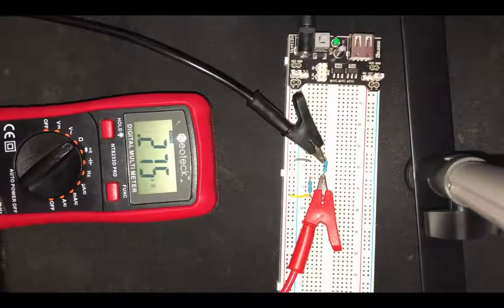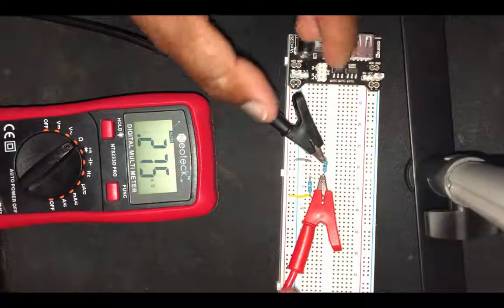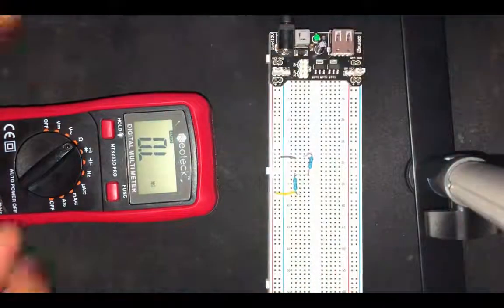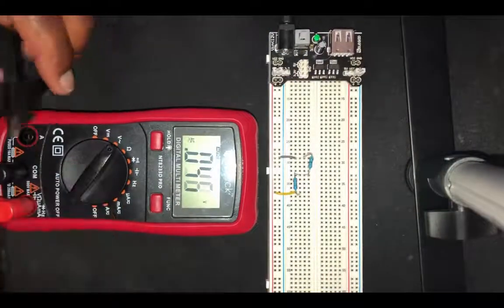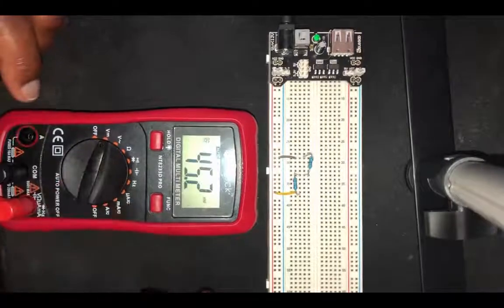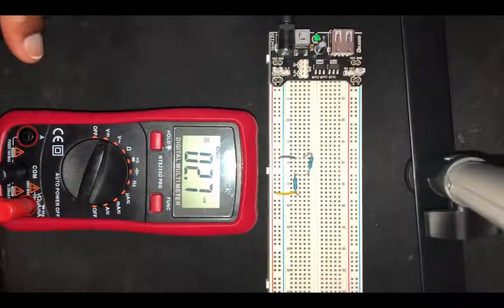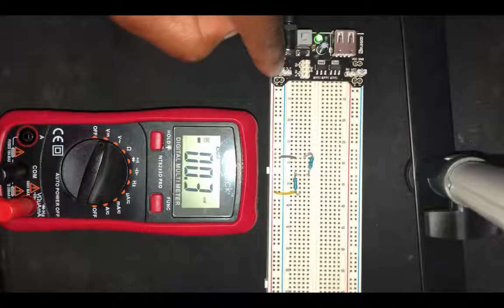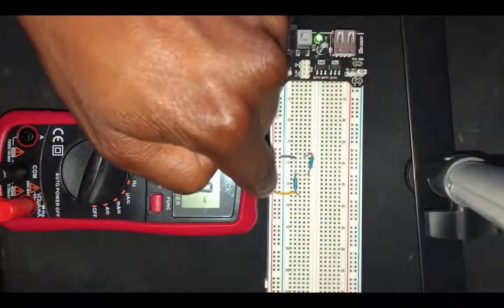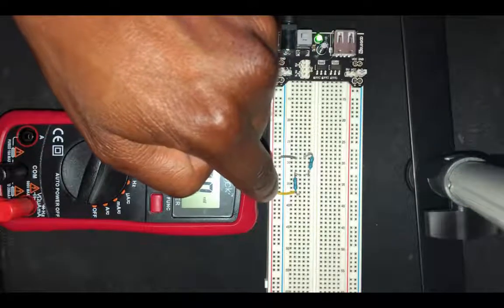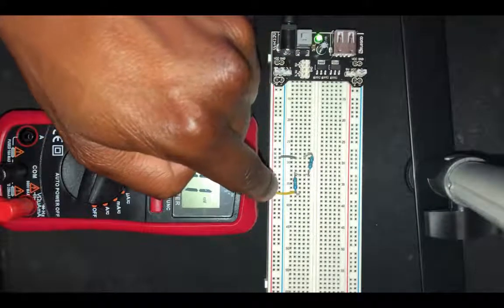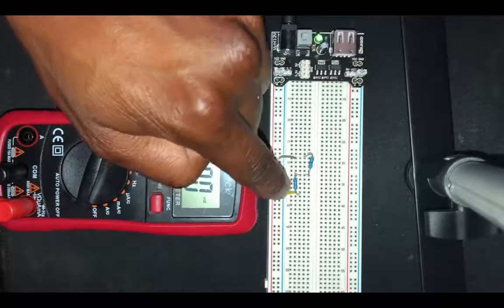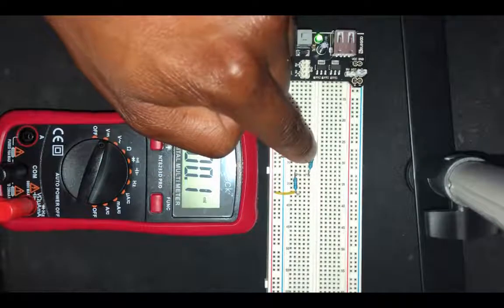276 ohms, okay. That's a slightly bigger discrepancy, but not game breaking. All right, so let's set this multimeter to measure DC voltage because we have a DC power supply here, and let's turn it on. So power is now going from this pin all the way down the red strip, and this yellow solderless wire feeds off of that power and gives 5 volts into the breadboard on this side. 5 volts, some of it gets dropped along there, some of it gets dropped along there.